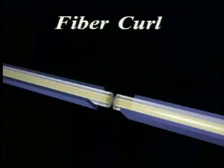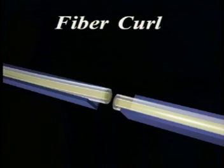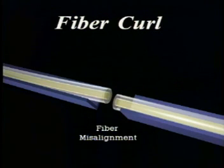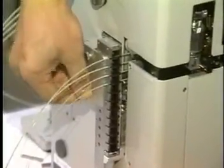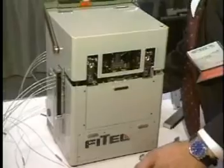Fiber curl describes the amount of curvature that exists along a given length of fiber. While all fibers exhibit some curl, excessive amounts can cause end-face offset in V-groove alignment fixtures. Concern with fiber curl was not an issue until the advent of mass splicing techniques used with ribbon fiber.